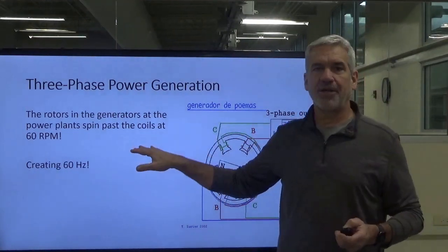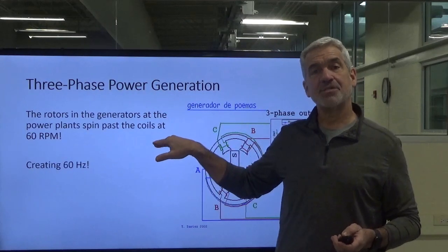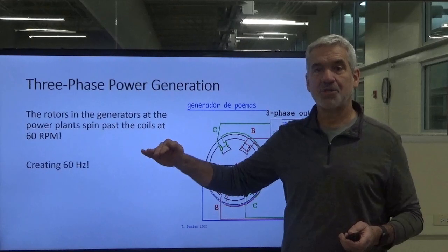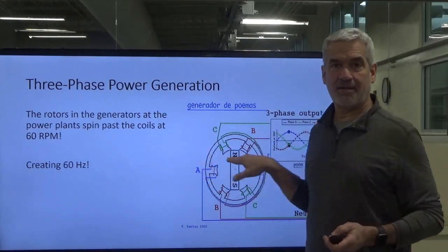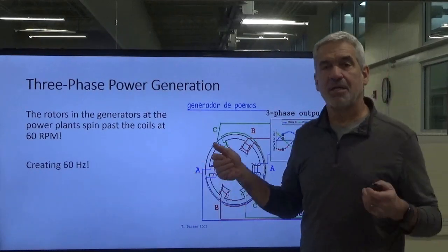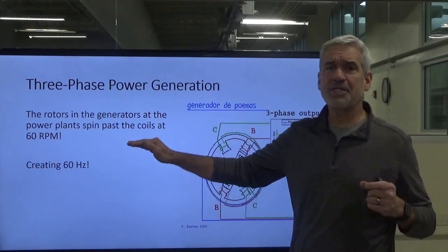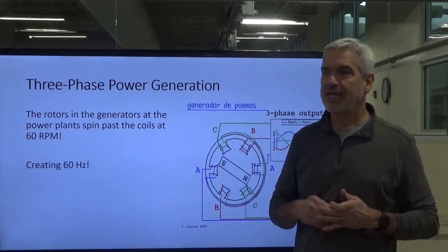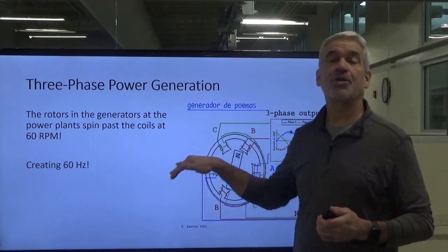So what we saw, though, is on microwaves, for example, the clocks were always running fast because they're designed to run at 60 hertz and keep accurate time at 60 hertz. If you run your house through that generator that's sitting out in the yard, you increase that frequency, then you're going to impact the functions of that microwave, okay? The table's going to spin faster, just a little bit. The clock's going to run a little faster, or it could run slower.